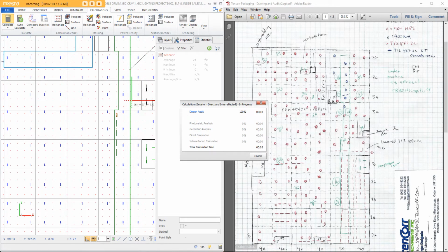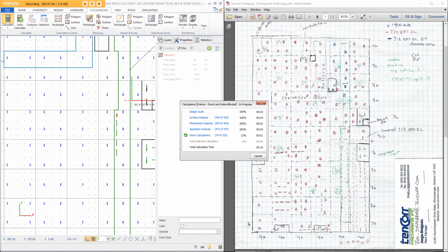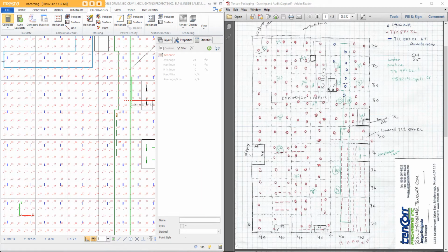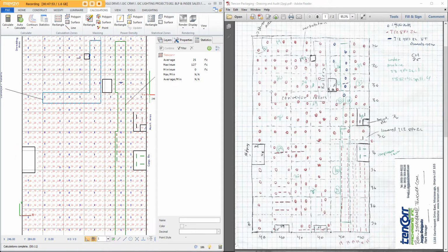Now you'll notice that there's some ceiling fixtures here, T12 8-foot 2 lamp along the ceiling. Those will all be removed. We're not going to replace those. Just utterly pointless because we have all these high bays in here. Looks like our light levels are beating the existing light levels in all the important areas. A little bit of a hotspot here at 37.